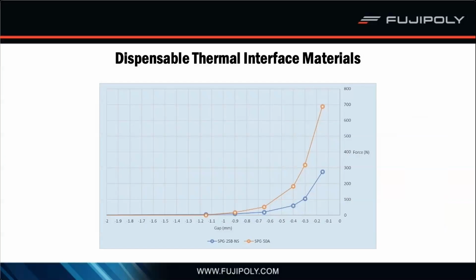One of the challenges when selecting and working with any thermal interface material often is managing stress. Specifically, how do you compress the TIM while managing the stress so that it doesn't cause any damage to the PCB, the solder joints, or other components? Most thermal interfaces require some pressure to work or create some kind of stress because of the deformation on the TIM. So with viscous materials like dispensable gap fillers, those concerns are greatly reduced when compared to a gap filler pad, but not completely eliminated.